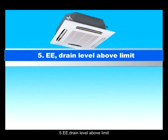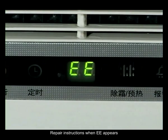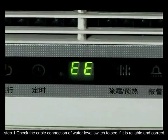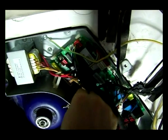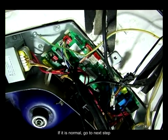5. EE drain level above limit. Repair instructions when EE appears. Step 1. Check the cable connection of water level switch to see if it is reliable and correct. If it is normal, go to next step.